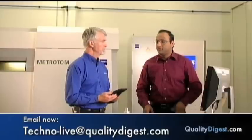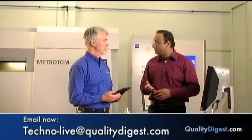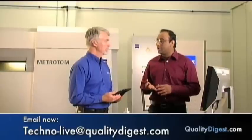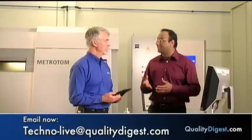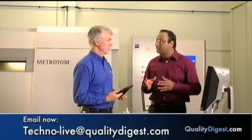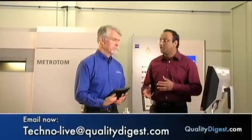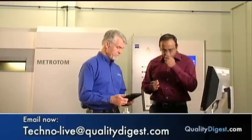But there are a few factors that drive the measurement: the amount of voltage, the amount of current, and what we call the integration time, which is basically how long you're exposing the part at each step as it rotates. So as long as you create a good balance based on the density and size of the part, you're good to go. So there's not a lot involved.